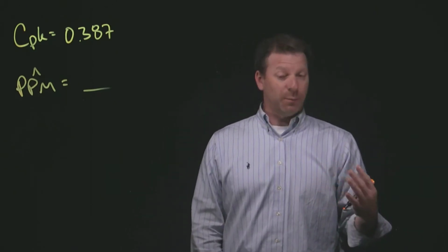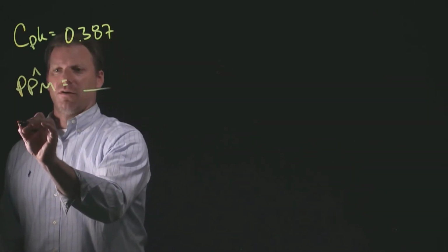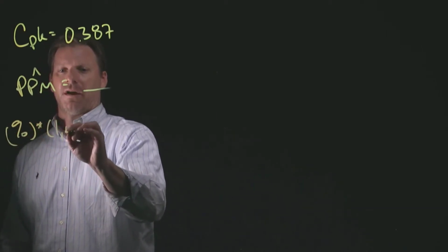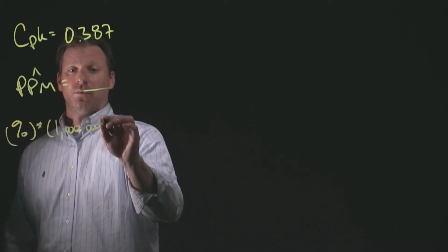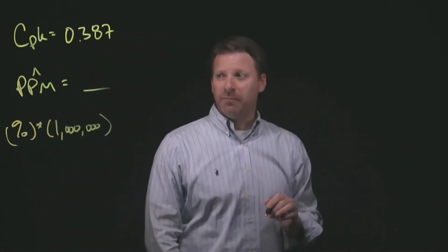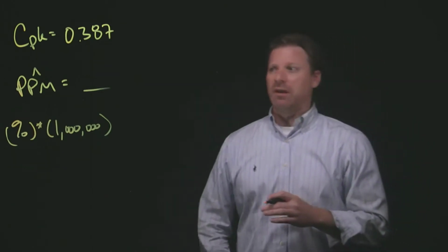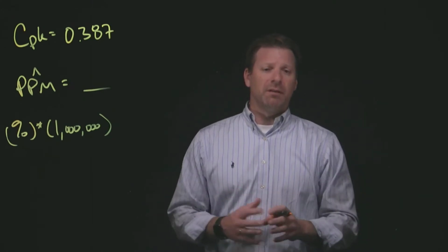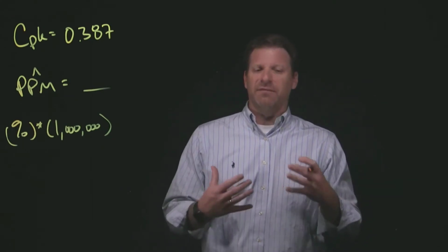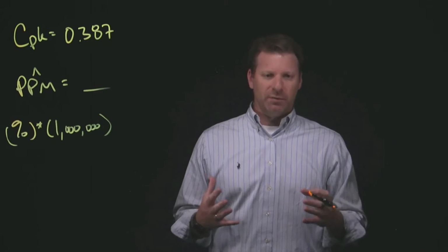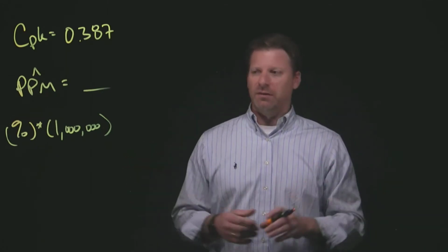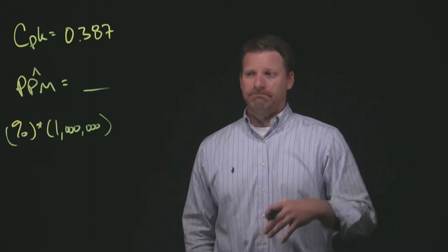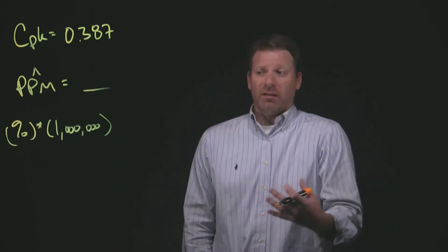It stands for parts per million. In our case, we're going to calculate some percentage of values, and we're literally going to multiply that value times 1 million. That's going to give us our PPM. The reason different industries use PPM is we can take very small decimals and multiply them by 1 million. It's like putting a magnifying glass on those numbers. We can take small decimals, and they turn into much larger whole numbers. It's literally just a way to shine a light on what's going on.